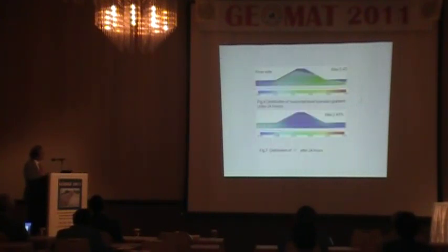And then I will show you the distribution of the hydraulic gradient after one day. You can see the maximum point here. It means the back side of the embankment. And this is the distribution of accumulated plastic shear strain. It exhibits the degradation of the material. So we can see 2.45% at the top of the embankment.